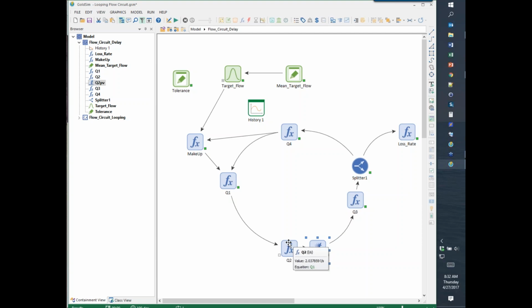And on the second calculation, the previous value element says, I'm going to capture the value that was calculated on the previous loop value. It's just whatever was updated last time, in this case the previous loop. And so it's no longer looking at the previous time, it's now looking at the previous loop. And depending on the complexity of your system, you will be able to remove any kind of delay that you're seeing with the previous value element.